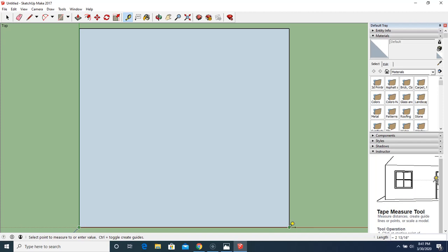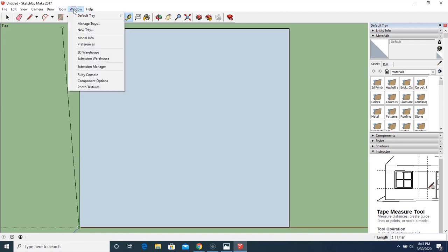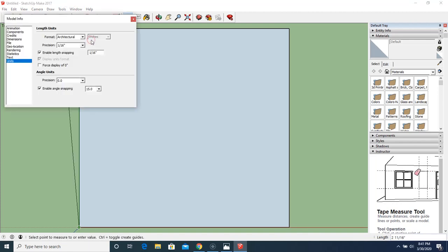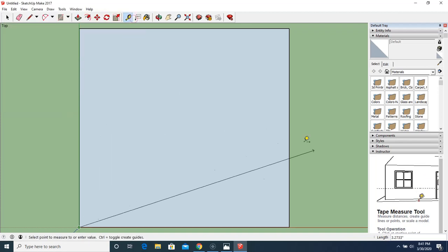And we've got our first adjustment that has to be made. This highlights the difference between mechanical drawings and architectural drawings, and also it shows that SketchUp defaults to architectural. So to make the adjustment, you're just going to have to go up to Model Information. If units are not default highlighted, click on Units, go up to this drop-down menu, pick Decimal, and then close the window. So we've got 2.8 by 2.65. Wonderful.